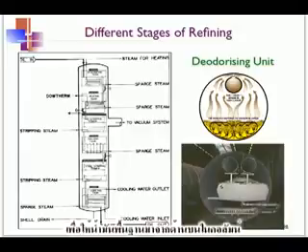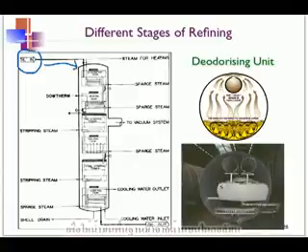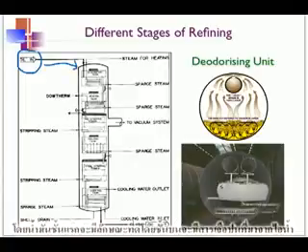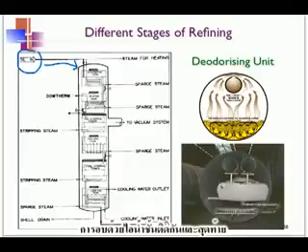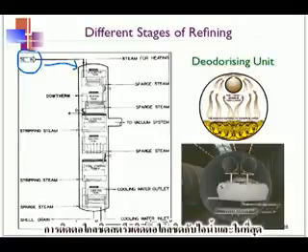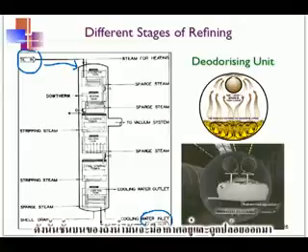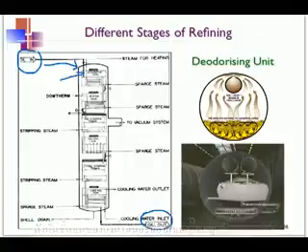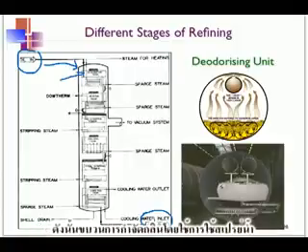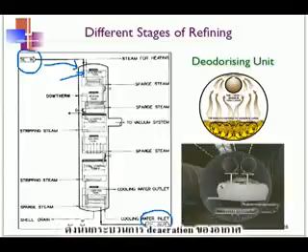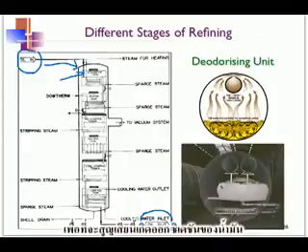So basically the oil comes from the top into the column, and will go through several stages of stripping of the volatiles when it comes into intimate contact with the steam, and finally it will come out here as the deodorized oil. So on the top part here is the aerating tank where the air in the oil will be removed. The aeration process removes the air so that it will reduce the oxidation of the oil during the deodorization